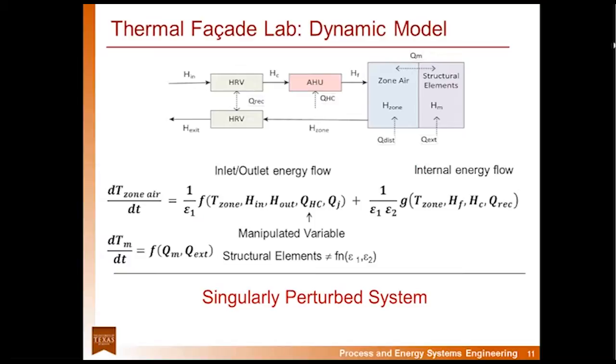This is exciting because the mathematical model can explain the multiple dynamics observed in buildings, and we can see that the multiple time scale behavior is due to the discrepancy between the air and structural elements thermal mass, and also because of energy recovery. I also should have mentioned before that rigorous first principles models for buildings also pose numerical